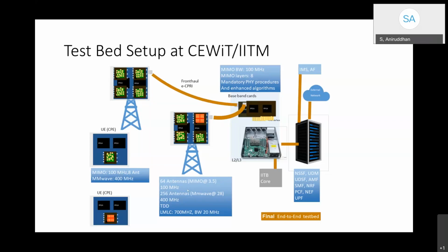In the case of millimeter wave, there are not that many users right now and the range is shorter. So you have larger groups of contiguous bandwidths. Therefore, you don't need many spatial streams. Typically it is expected that for a single user, you will use only one spatial stream.